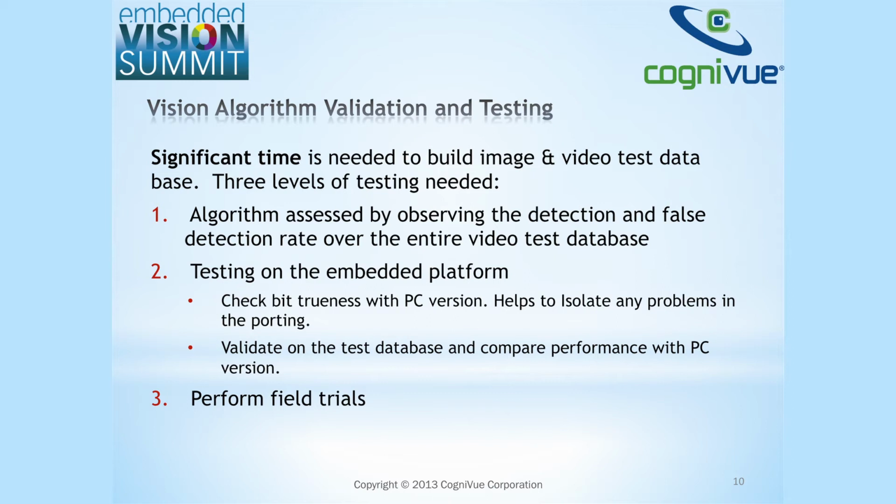And we found, of course, 3 levels of testing were needed. Assessing by observing the detection and false detection rate over the entire database. Testing on the embedded platform, okay? Checking for bit trueness against the PC version of the algorithm. Validating the test database and comparing the performance against the PC version. Okay, so you're going to test what you've done on the PC, what you've done on the embedded platform, and make sure that you're getting the same number of true positives, eliminating the false positives, et cetera. And then ultimately you get to the field trials, which is even more time consuming.